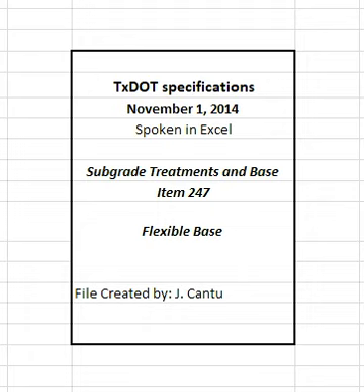The final product, blended, will be subject to the requirements in Table 1, and for final product, unblended, 100% department furnished required recycled material, the liquid limit, plasticity index, wet ball mill, and compressive strength is waived. Crush department furnished RAP so that 100% passes the 2 inch sieve. The contractor is responsible for uniformly blending to meet the percentage required.